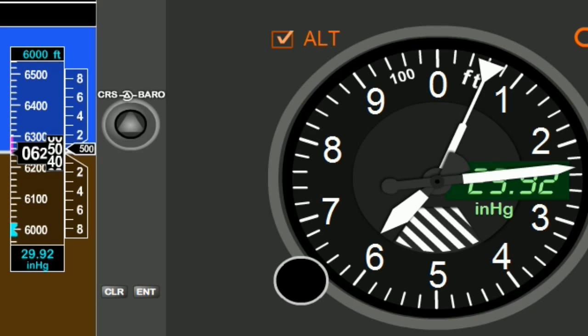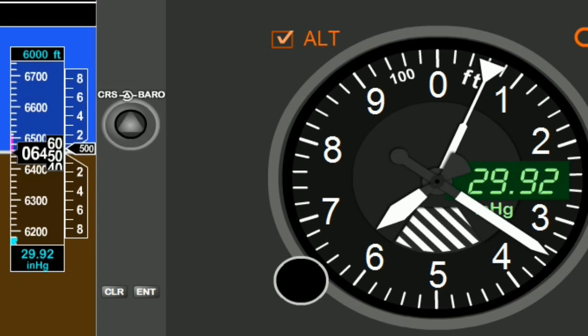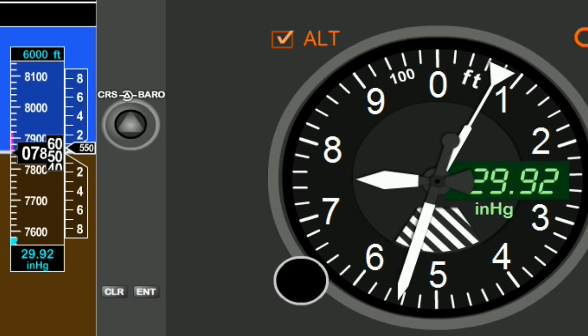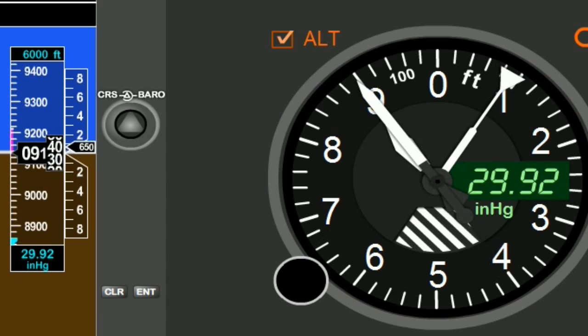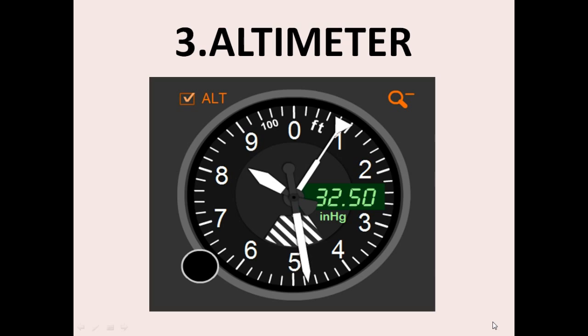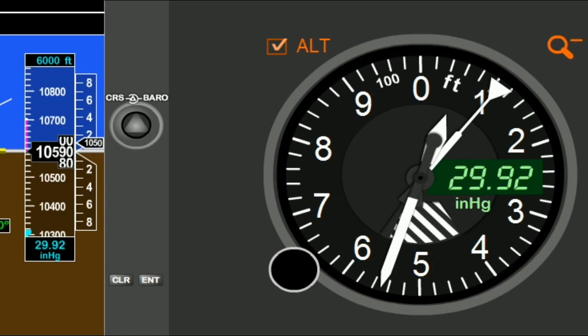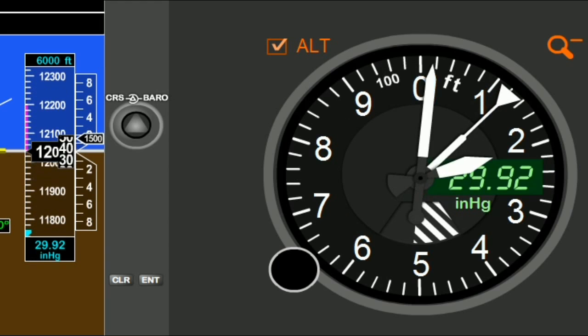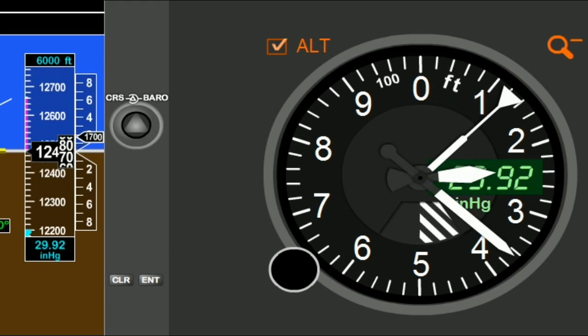That is the first needle, the biggest among them, the biggest needle points up to 100 feet. Then the second one, it points from 100, 200, 300, 400 until it shows about 10,000. And the bigger one, that is this one, shows the height from 100 to 10,000. It means that if your aircraft moves 10,000 feet, the one with this inverted funnel like thing here will move from 0 to 1. If it moves 20,000 feet, it will move from 1 to 2.